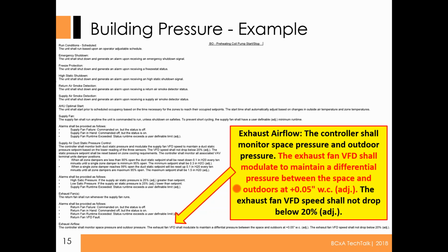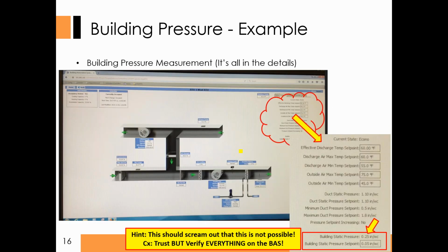in your sequences. So they're going to have supply air going in, and they're going to modulate the exhaust to maintain a positively pressurized building. This is a completely acceptable sequence of operations. This should work just fine. Okay, and then don't let it drop below 20%.